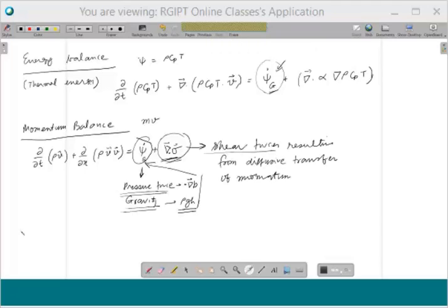Navier-Stokes, well, it becomes Navier-Stokes when you next apply how you express sigma in terms of mu. So for linear fluids you write sigma equals mu times del Vi by del Xj plus del Vj by del Xi. Substitute this, then it becomes the Navier-Stokes equation. Absolutely.